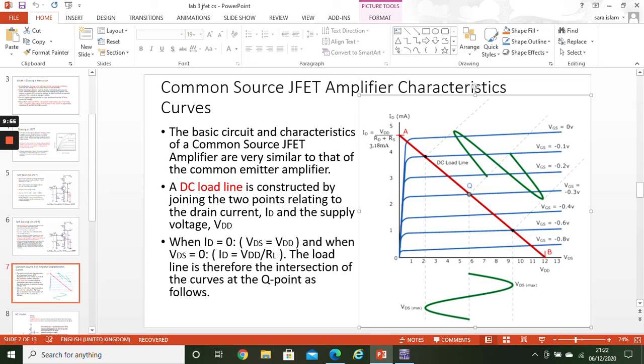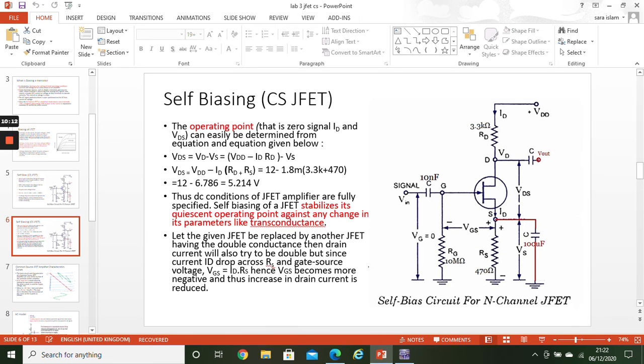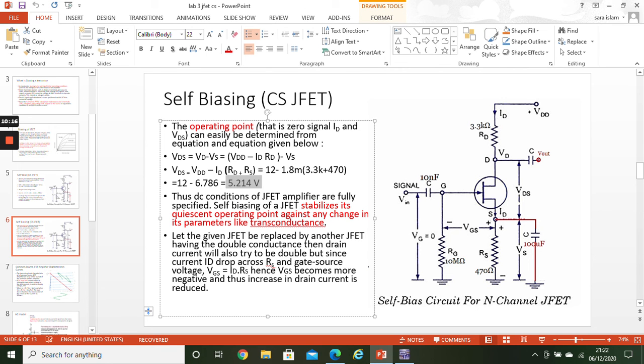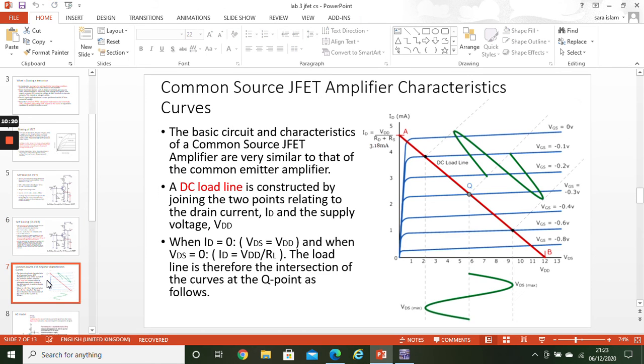And if you go such that half of it is clipped, not exactly half, then you get class AB and B. You are familiar with those concepts. So the whole amplification procedure totally depends upon your quiescent point, which point you are using, what is your VDS voltage. Presently in this scenario, our quiescent point according to this set of voltages is approximately mid. It means presently we will be using it as a class A amplifier.